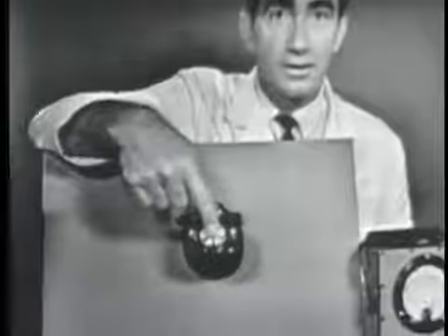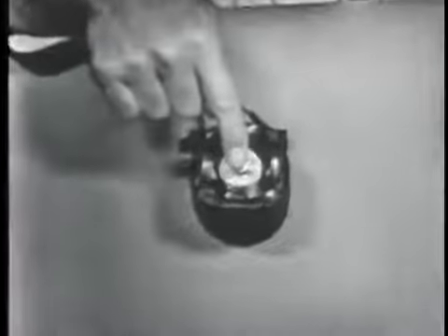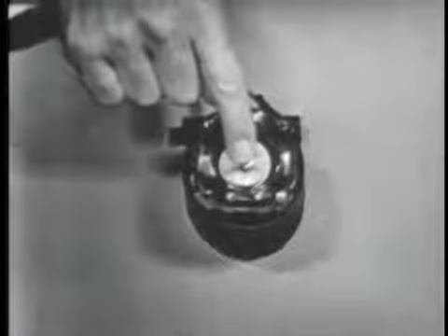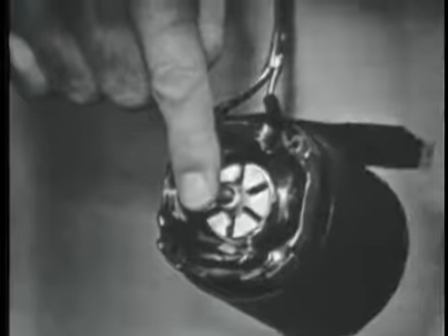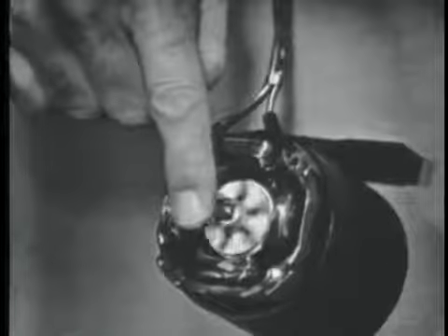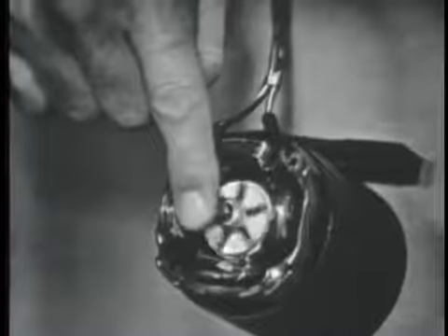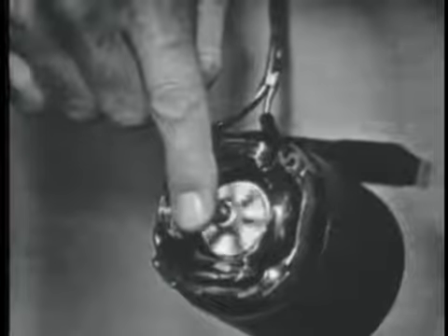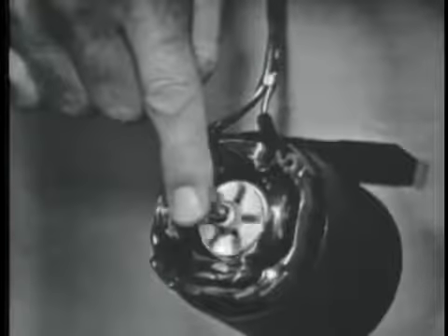The load of the fan causes the rotor to slow down, just as I can do with my finger here. I can cause the rotor to turn slower. Now, as it slows down, the slippage increases, and the frequency at which the conductors of the rotor are cut by the rotating flux lines increases. More current flows, and the magnet becomes stronger and compensates for the increased load.